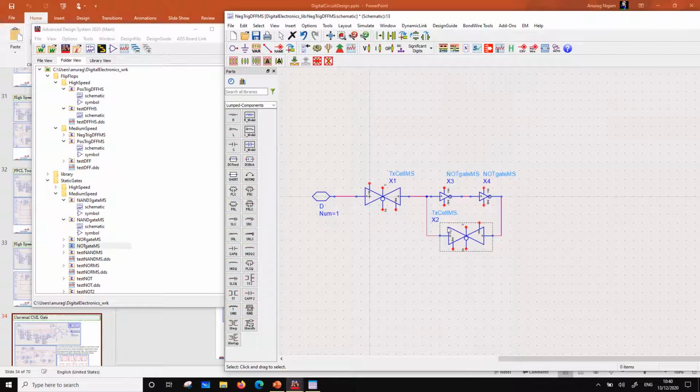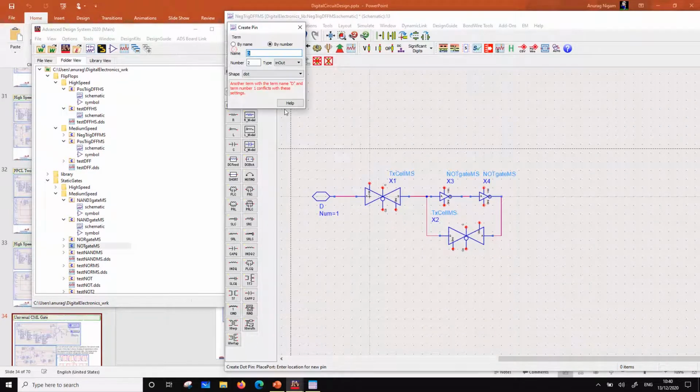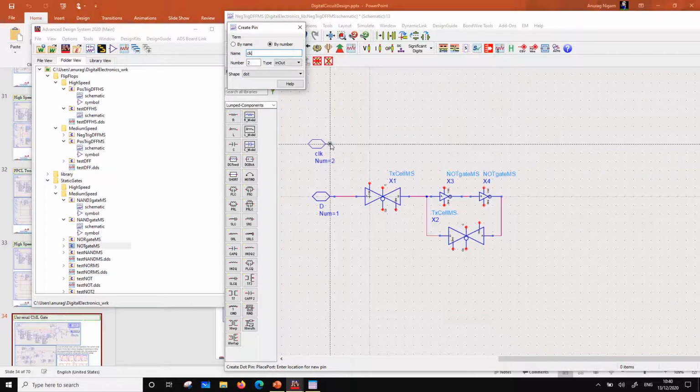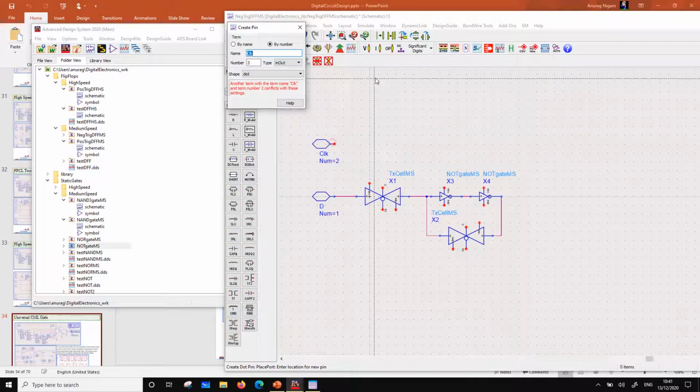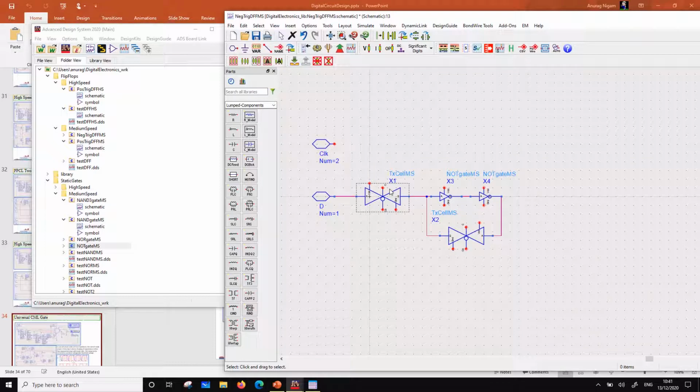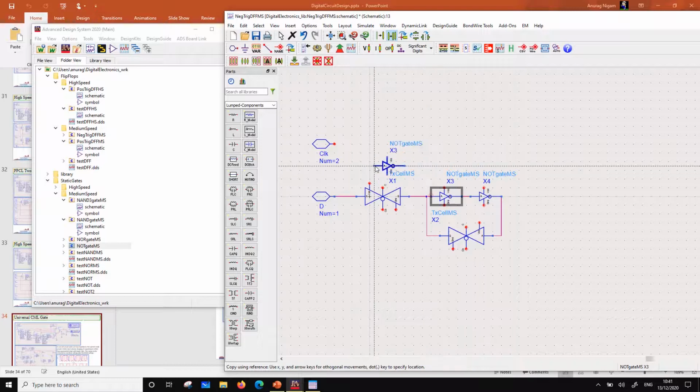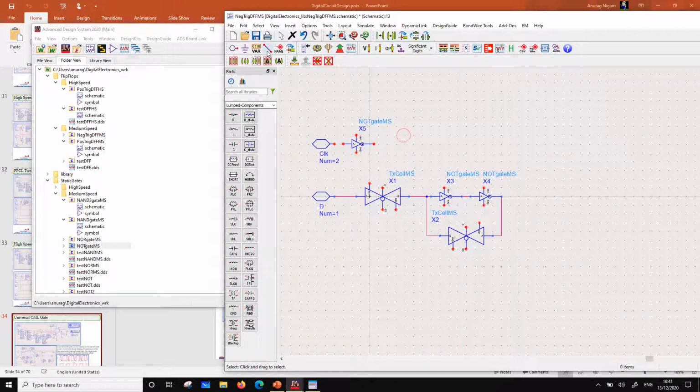Now this is going to respond to positive edge, right? So if I put a clock here, this is going to be capital C. Okay, so this is a clock. And then I will put another inverter here to do a clock bar. So this is going to generate a clock and a clock bar. I'm going to name them: this is going to be clock, and this is going to be clock B.